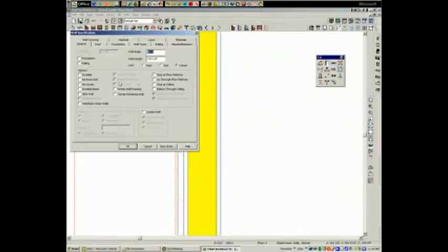Also, this wall here needs to be set as an attic wall, so since I drew it manually, you have to set these attributes here manually. I want attic wall retain, no locate, no room define. Those are the default attributes of an attic wall.